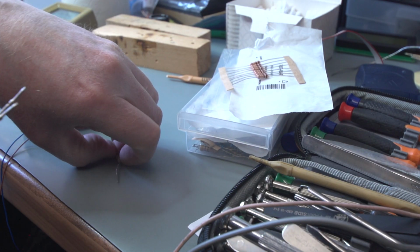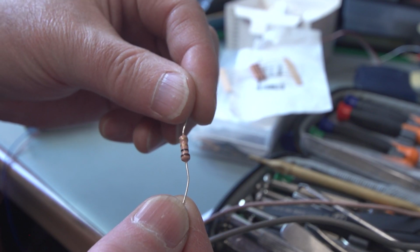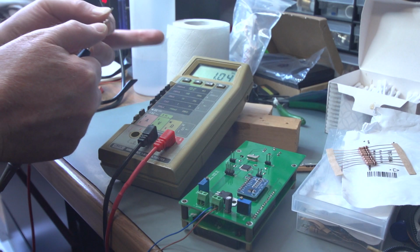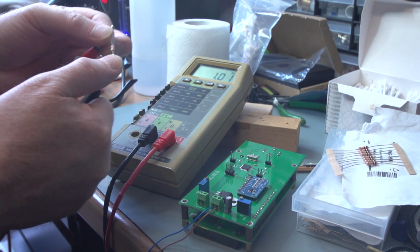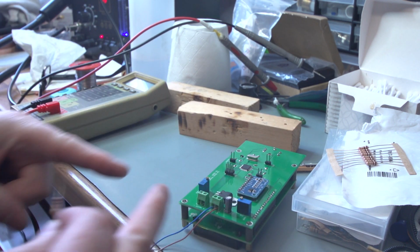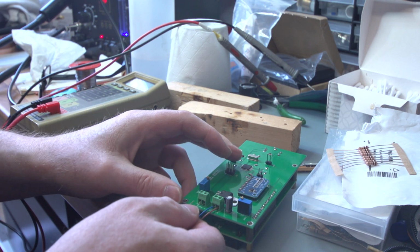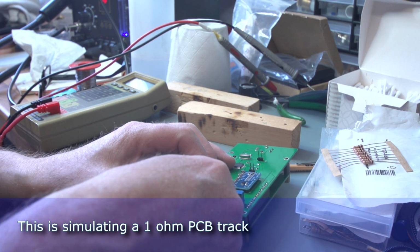So I've just picked out a 1 ohm resistor. It's a double gold, so we'll check that on the meter and see what sort of value it's given us. 1.04, 1.02. Yeah, it's pretty accurate. Slightly over 1 ohm. Let's put this straight into the terminals where the probes go. Check it against this 1 ohm resistor.